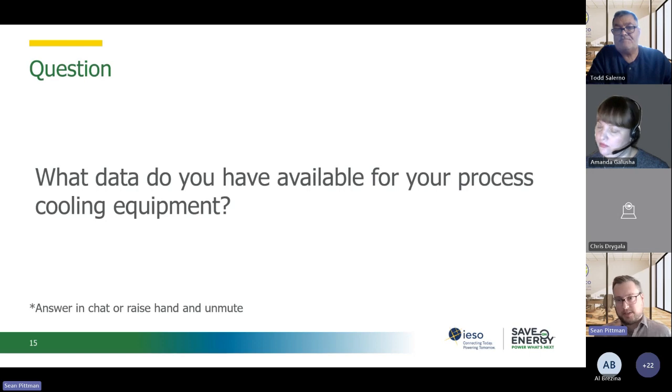The other is, this sounds like you're specific to categorization, that you're not meeting certain thresholds for either uncertainty or accuracy that are requiring you to report these projects as M&V not possible or savings assumed. So it's difficult to say what the specific factors are, but what I would assume those factors are probably interval meter data of energy consumption, chilled water flows, and chilled water return and supply temperatures.